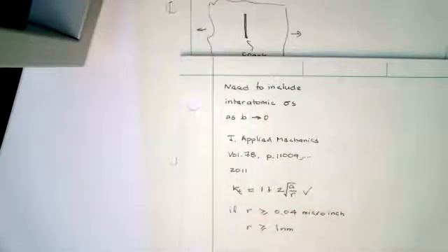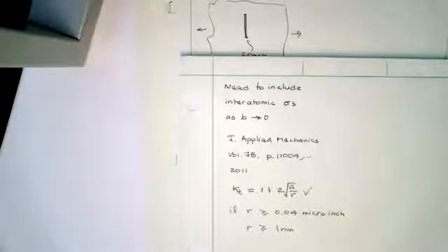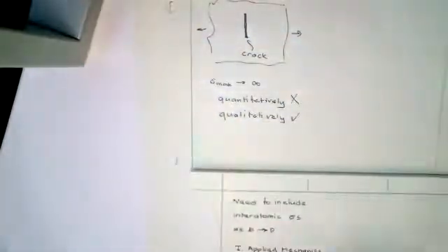If you've got something with a small radii and you go measure it, you're going to get something bigger than this. This sort of formula will work. You get very large stresses. The good news is that they operate over very small regions, and sometimes you get strength size effects that help you out. We can also use this for extrapolation on your charts when you have small radii. Let me show you.